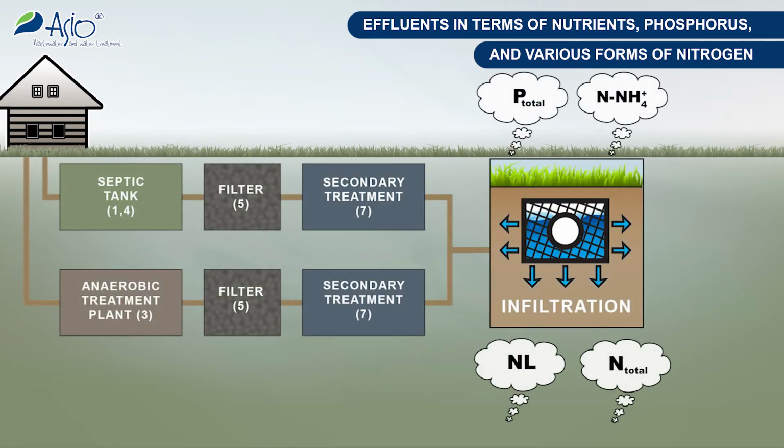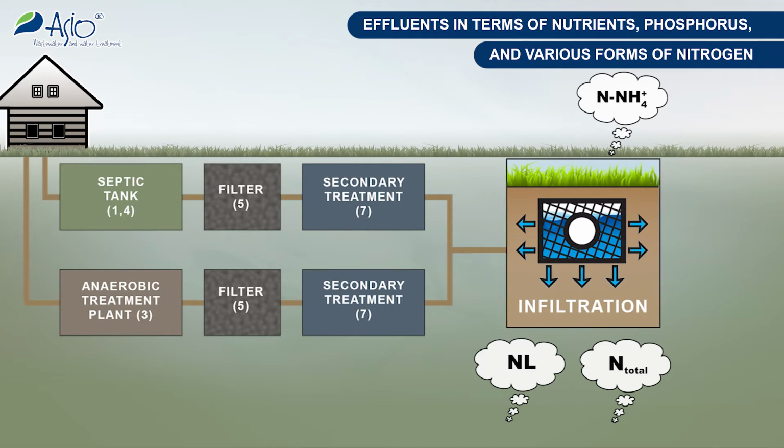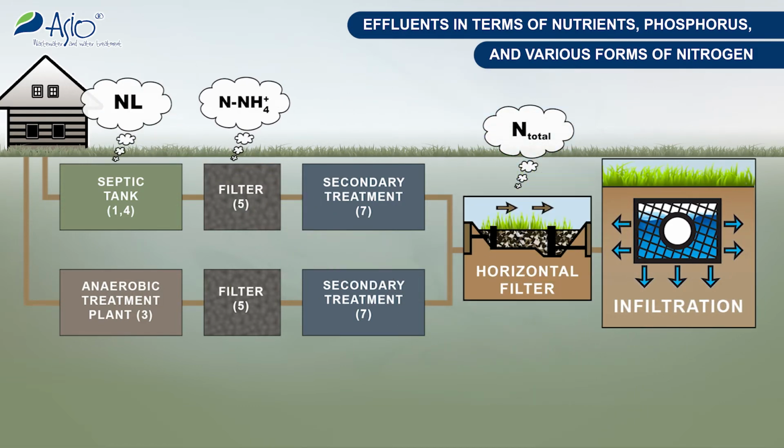In view of environmental protection, it's not excessively important to be particular in the phosphorus removal if the cleaned effluent is discharged to underground water bodies, because phosphorus is trapped in the soil anyway. On the contrary, it's important to eliminate insoluble matters and provide for a complete removal of nitrogen in the downstream denitrification stage, for example, by a horizontal filter.